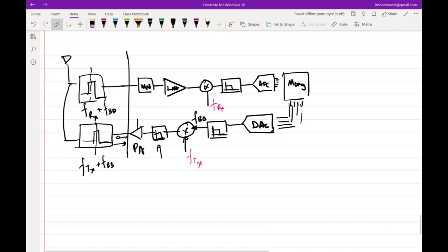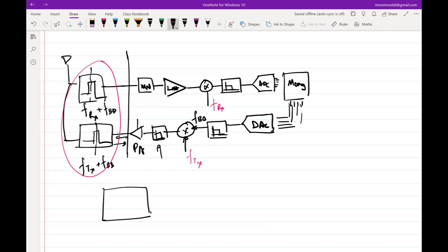So quite often, again, you are going to see in architectures, if you look at data sheets of transceivers, that these two are also combined into one single filter, and that's called a duplexer. Two SAW filters combined together. It's called a duplexer. And I shouldn't say two SAW filters combined together is called a duplexer. A duplexer is something that allows signals to flow in one direction and not the other in some way. So that is ensured to some extent by,